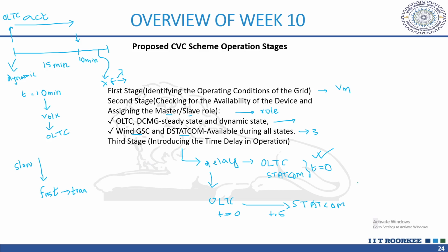And okay, that is one thing. And the second thing is why we are not simultaneously activating the STATCOM and OLTC at t equal to 0. If we know that at t equal to 10 that voltage is required, if we start both of them simultaneously, it may happen that there will be, we say, a hunting effect.